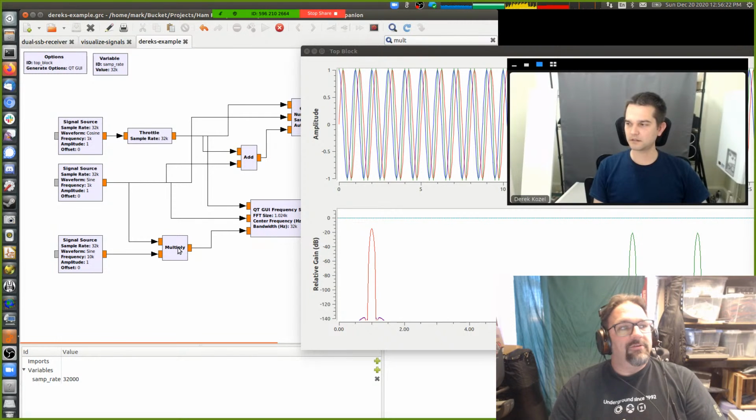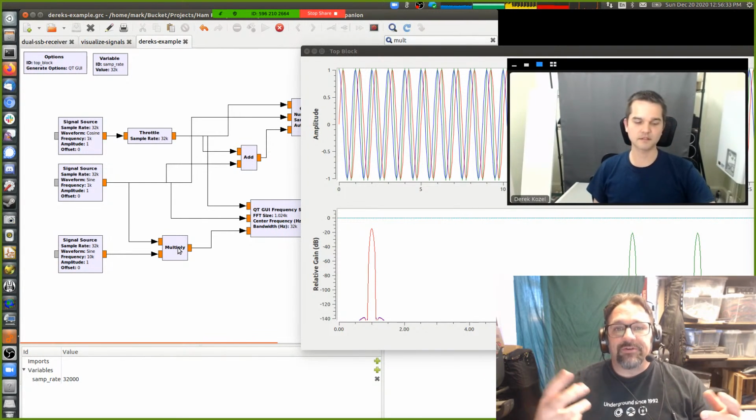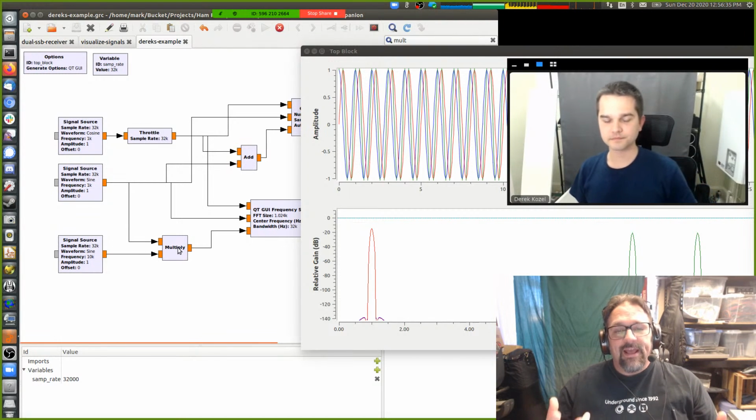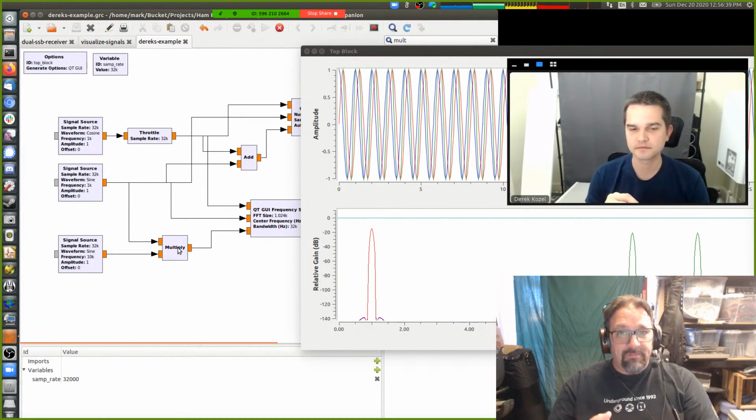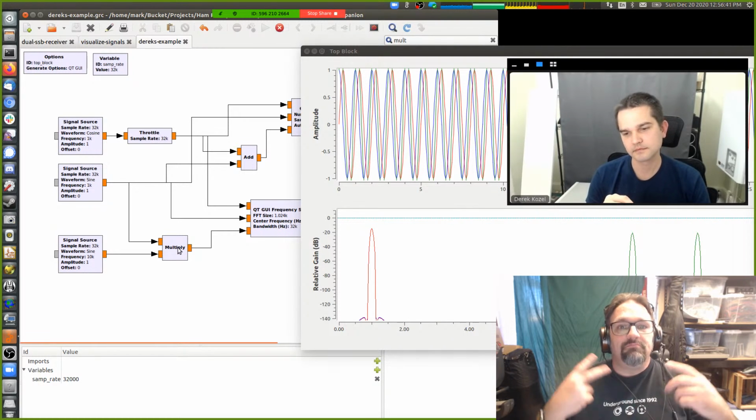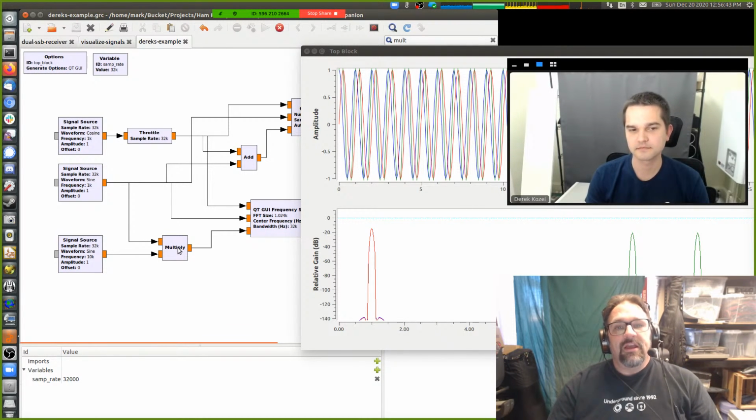And when you are in hardware and you have a mixer in the RF sense, not a mixer in the audio sense, but a mixer in the RF sense, which is a product mixer. Product meaning multiplication, right? As opposed to the sum meaning addition. So instead of a summing mixer, this is a product mixer. It is multiplying 2 signals together. If you look at what a mixer does, it basically multiplies the 2 signals together.